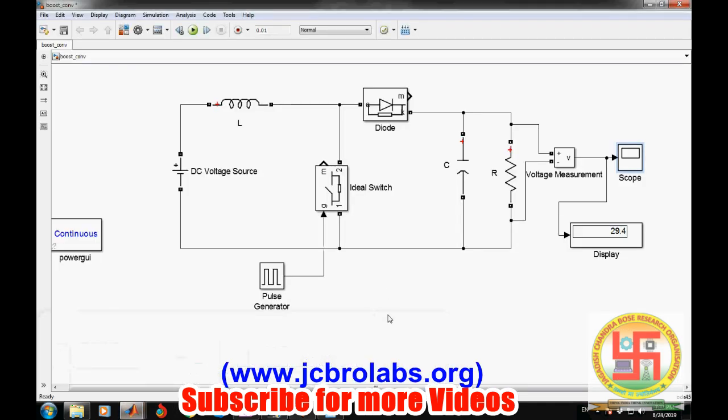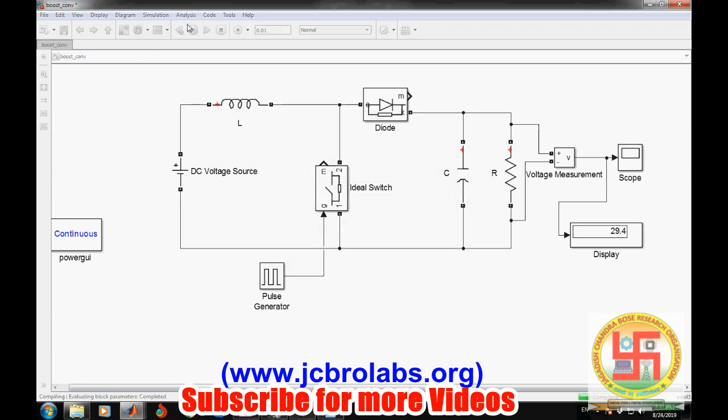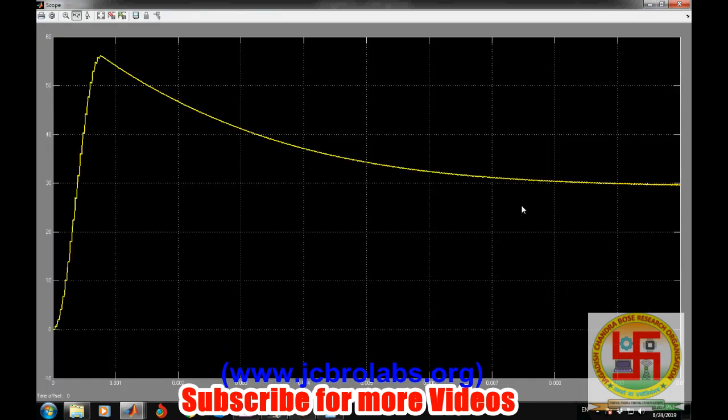So let's change certain values of it. Because this was the minimum value which was required, let's say I have a 100 microfarad capacitor, and let's see what happens to the ripples. Yeah, you will find now the ripples are less, and it is closer to 30 volt. And if you auto scope, you can visualize the value of the ripples as well.